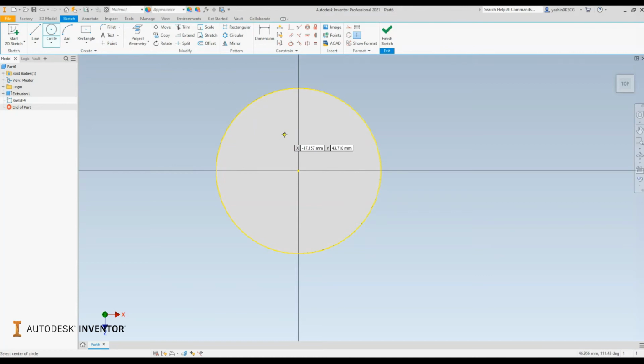Okay, so I can specifically size the circle while I'm drawing it out by simply defining its center position, and that center position can be points. You can use them as a reference, for example if you were creating a hole. However, in this case, what I'm going to do is actually assign it a value. Okay, give it a diameter.